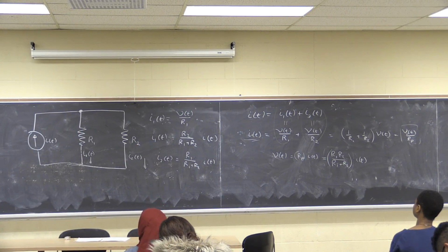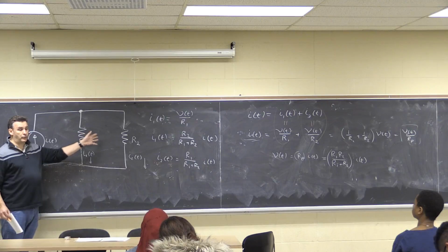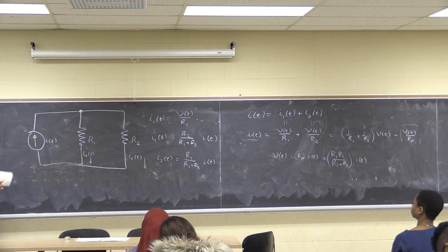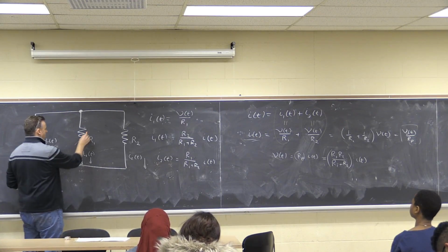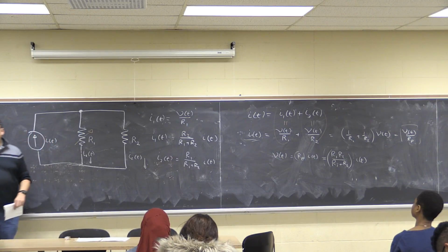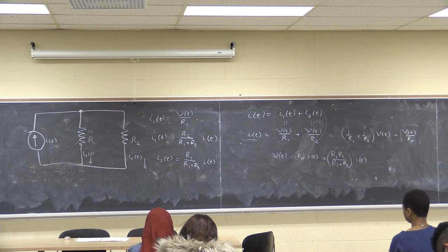So if I've got two equal resistors in parallel, driven by a current, I get the same current through each. Likewise, if I make one of these a variable resistor, the sign for a variable is having an arrow drawn through it, I've got a variable current source. So the current through R2 changes as I change the value of the resistance R1.